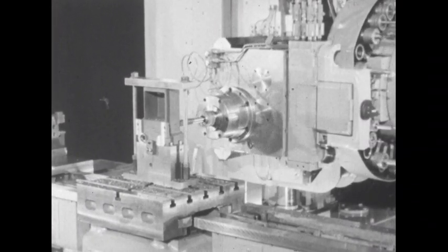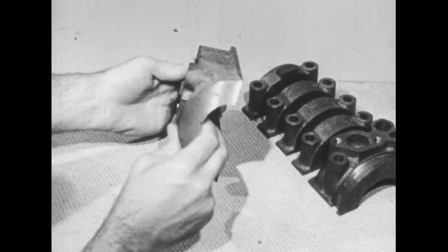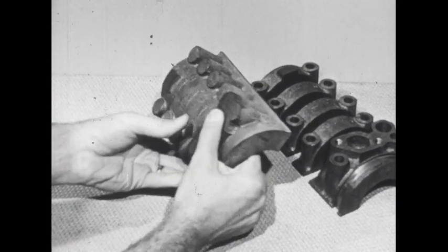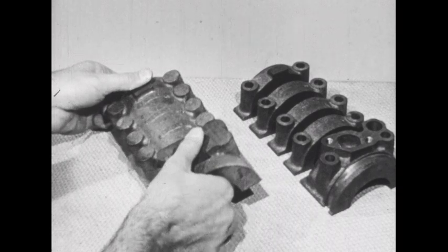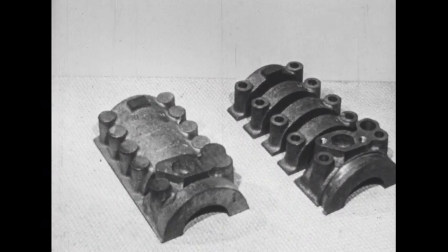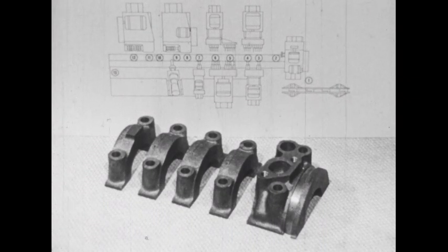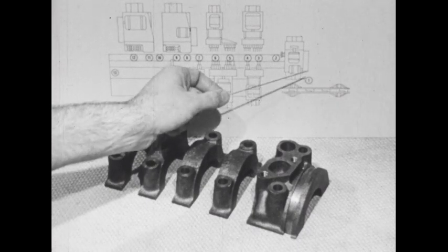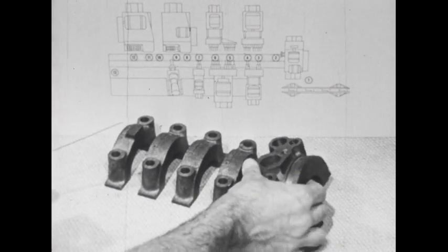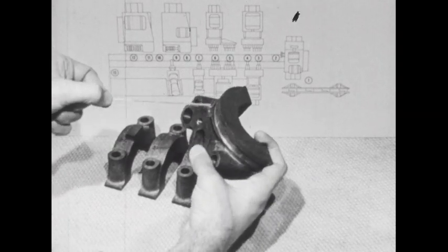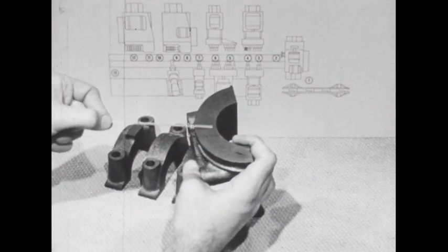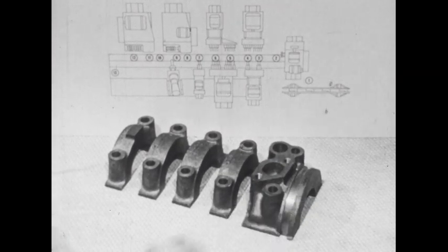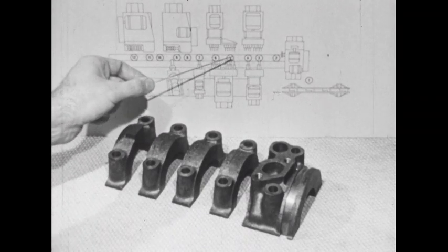There are some cases where many thousands, even millions, of interchangeable parts are required, as for instance bearing caps for a series of automobile engines. In such cases, it may pay to engineer a special machine for the job. This casting is to be machined as one unit and then split into a set of bearing caps. This is a schematic drawing of a Kearney and Trecker transfer type machine, especially designed for machining the bearing caps. Castings are carried through 13 stations, and at each station, one or several machining operations are performed.